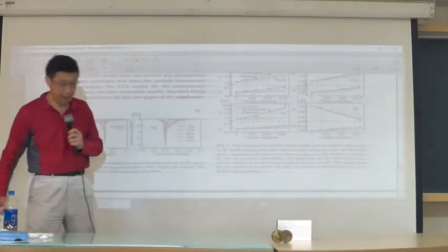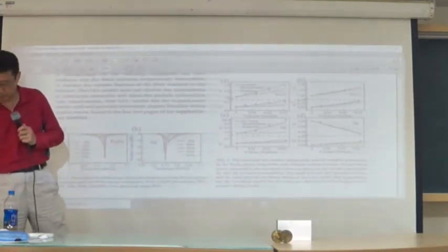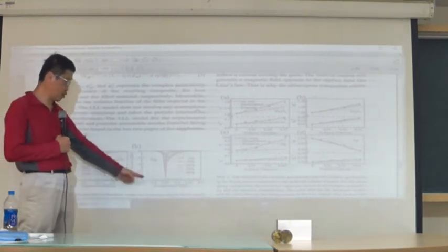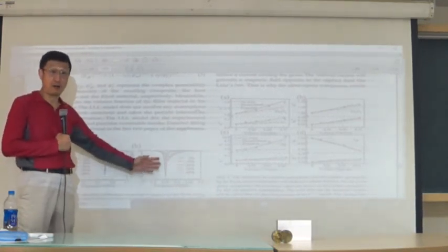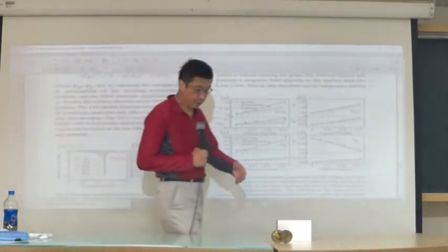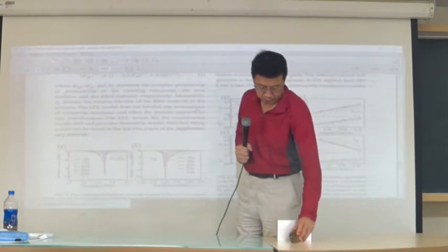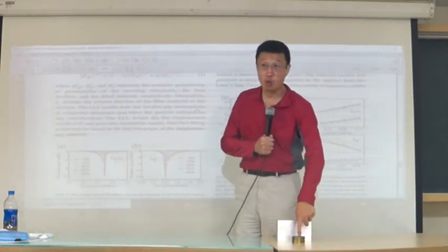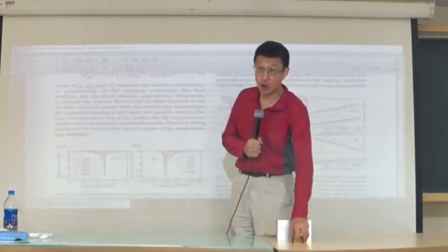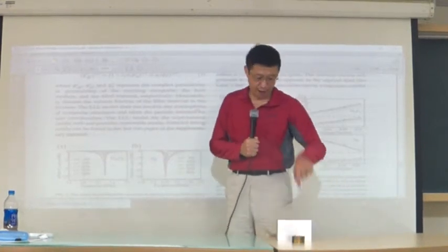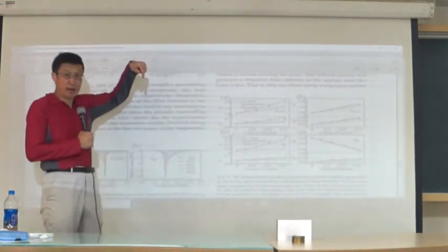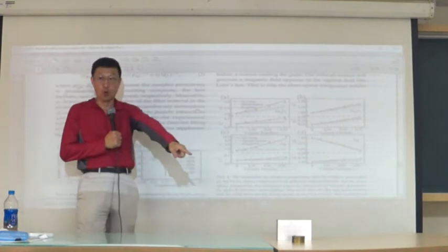And then you can see here, we can measure the resonance frequency. That's the frequency domain. From the frequency domain, we can measure its response. We inject a wave here using a coaxial SMA waveguide. We couple the signal from the top and excite the waveguide mode.